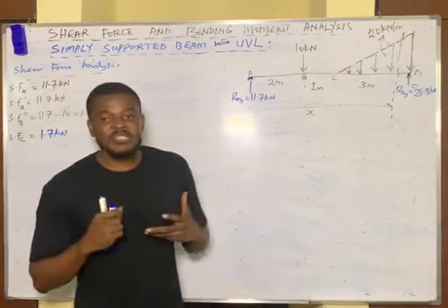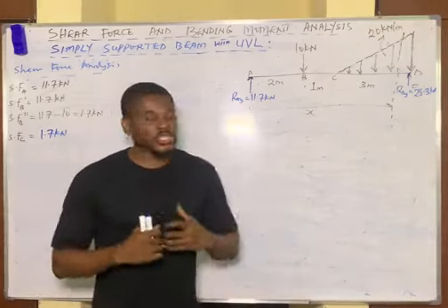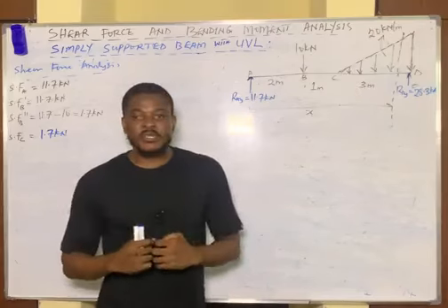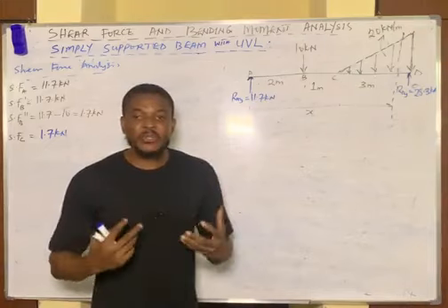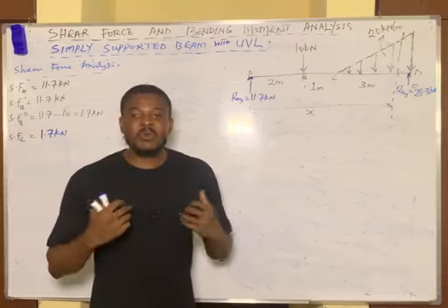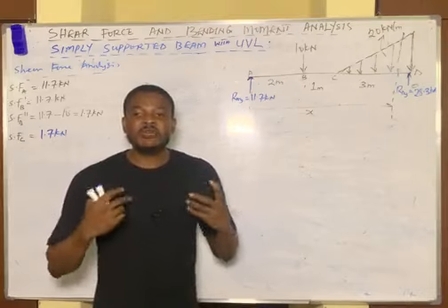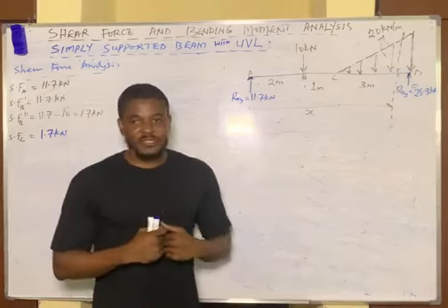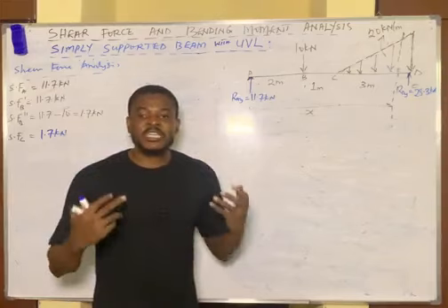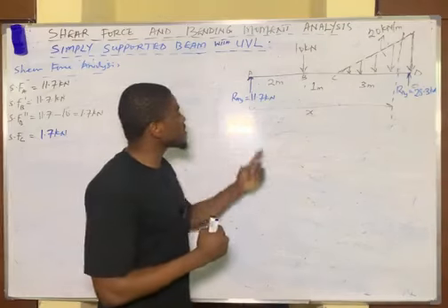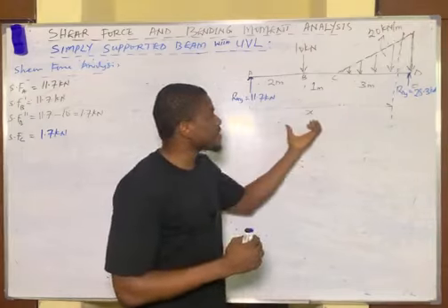The reason why we are doing this is simply because the shear force diagram and the bending moment diagram will change structure or shape when it gets to this strange type of loading. For that reason, that will require us to find what is called the point of maximum bending moment and the point of contraflexion. To find the point of maximum bending moment, you need the shear force equation. Then to find the point of contraflexion, you need the bending moment equation. And that is why we are doing this, right? So with this, you can get the shear force equation and also the bending moment equation. So if you're taking distance from point A to the point of the UVL just before it gets to the end, you call that distance x.